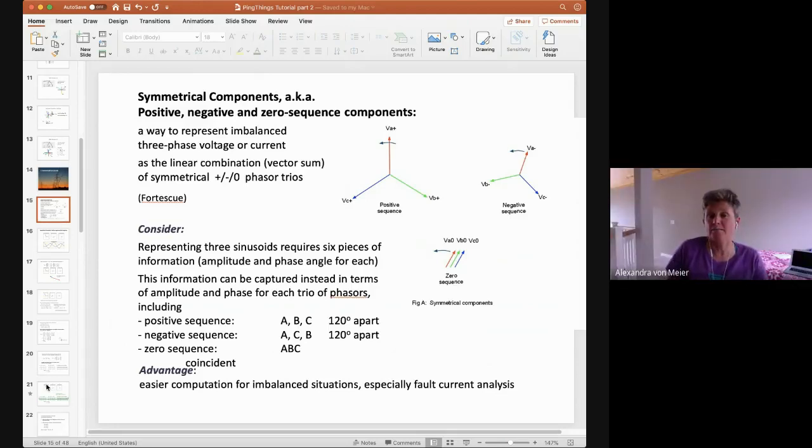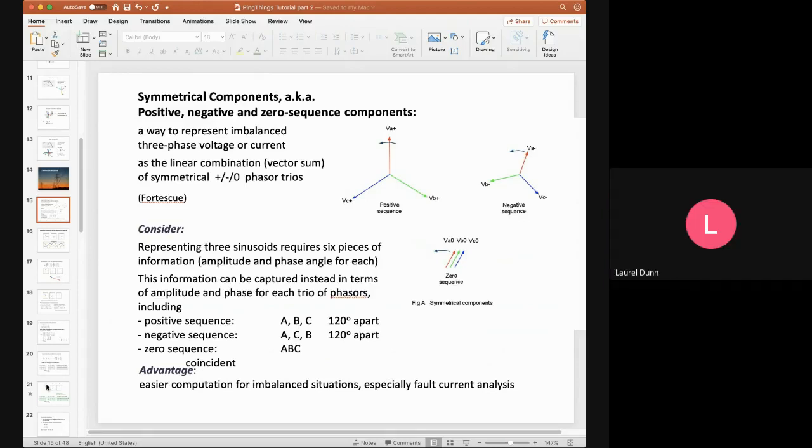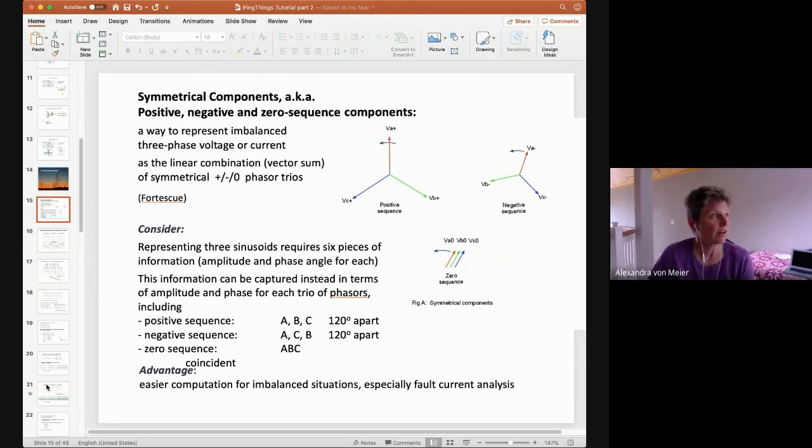And there hasn't been historically an infrastructure for doing that, because streaming phasor data alone has been thought of as a big deal in terms of information transfer, bandwidth required and storage required. So when you now go to point-on-wave measurements, continuous point-on-wave measurements that tell you all about the waveform, that's another order or two orders of magnitude more data. Now, one way around this, and if you're interested, read Harold Kirkham's stuff from PNNL.